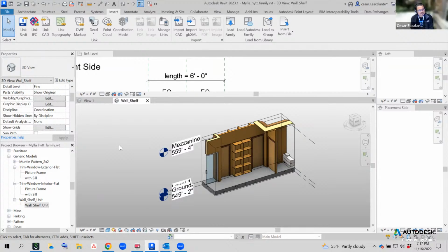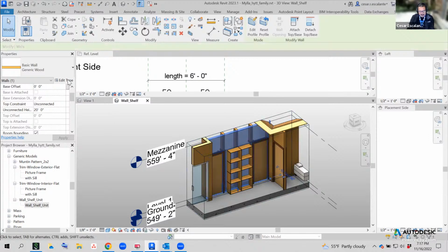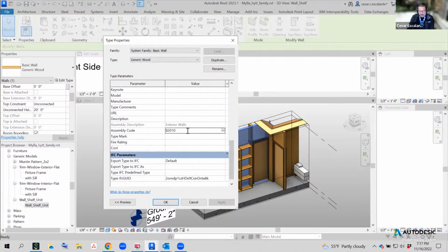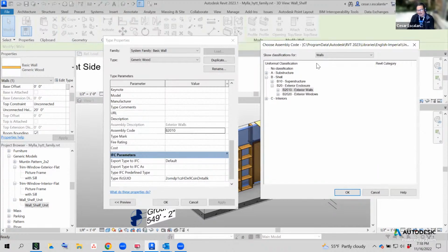Yeah, I think the tools have evolved robust enough to associate element instances with material specs. It's the way it works right now. The assemblies in Revit are connected with an assembly code that is associated with this classification system. But this is the out-of-the-box one, and this is Uniformat, which I don't think is as widely popular as MasterFormat. And what the tool does is, instead of connecting with the out-of-the-box assembly, it connects with the SpecMaster spec database that is part of the features of SpecLink.